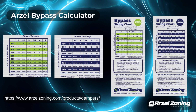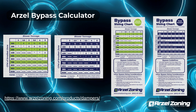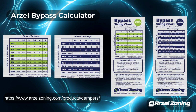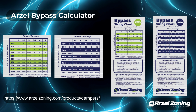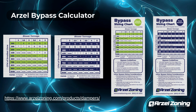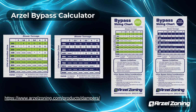At the bottom half of the card, it says other bypass sizing considerations. If you're using the calculator and you're unsure or you're kind of on the fence on whether I need an 8 or a 10 or I need one or I don't need one, the other bypass sizing considerations make you look at different factors of your system. Is there flex duct?